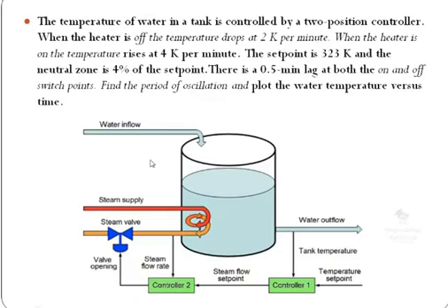Okay. So what we can do here, we can give the heater here, and water inflow, water outflow. We are measuring the temperature of the outlet water, and that is given to the controller. And the controller will decide the steam valve, whether we can give input or not. They are not directly giving the heat, just by means of sending the steam, they are increasing or decreasing the temperature. They are not directly giving the heat with the help of a heater, right? That will be controlled by the steam supply. Steam means heated water. So I am sending heated water or heated gas inside, and that will give the temperature or heat to the water. The steam supply will be controlled by this heater. So we are switching the heater on or off. That will affect the steam supply, right? And that will control the temperature of the water.